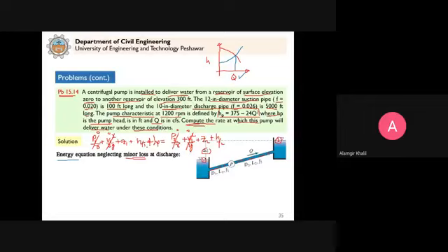So in here what we say is that Z1 minus Z2, that is your delta Z, which is given 300 feet. So this is given to us, Z1 minus Z2, this is 300 feet. Now when you simplify this equation here, the F value, the friction factors, are given for both the pipes, so you will get this equation. Clear? You will get this equation. This is delta Z, 300 feet, which is given, this one here.